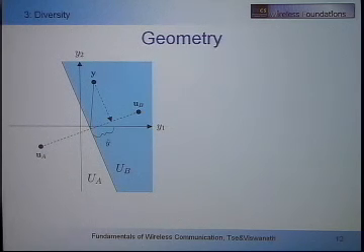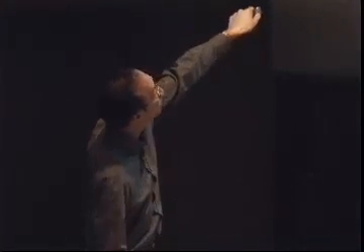Now, in general, what I'm doing here is transmitting information in terms of vectors. So here, I'm sending two vectors, uA and uB. And I want to be able to detect whether uA or uB is transmitted. This is the same problem as the BPSK problem, except now I'm sending vectors instead of scalars. 2 points. I need to figure out which one of the 2 points was transmitted. The optimal detection rule is, of course, to choose the one which is closest to the received vector, in this case, uB. So in terms of this picture, what I'm doing is drawing the hyperplane which is perpendicular to uA, uB.